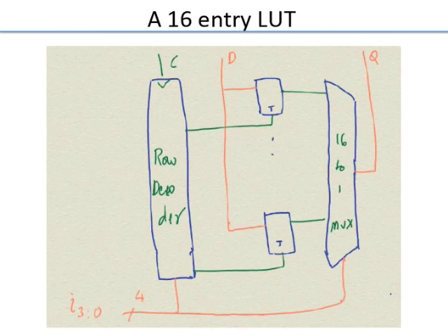Here there is no counter, because this is random access. Whatever 4-bit address is there, the appropriate word line gets activated. Then why do we need the clock? Because I want the word line to go high and come down. If I want that pulsing in the word line, then I have to create that pulse. Now, whether you need it for this particular case, suppose you don't have that. Then what happens?